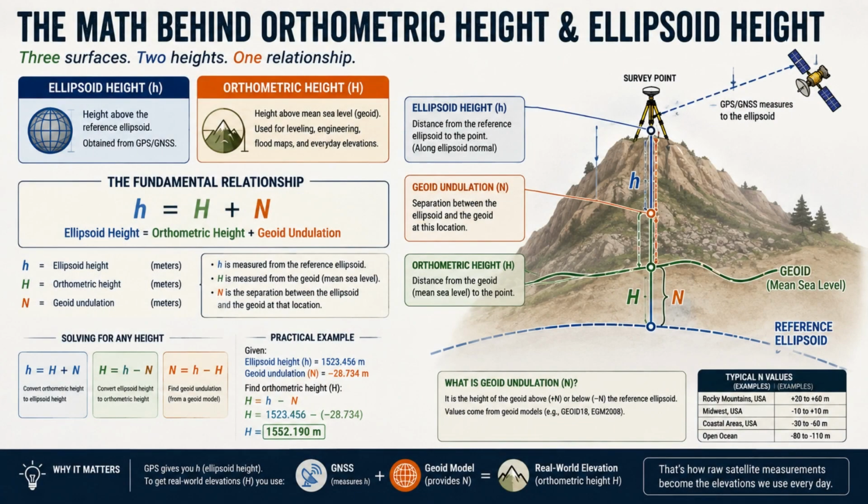Oh, right, going back to the Iceland and India examples. If the physical geoid bulges above the reference ellipsoid, like in Iceland, the geoidal height is positive. But if the geoid dips below the ellipsoid, like the gravity deficit in India, the number is negative.